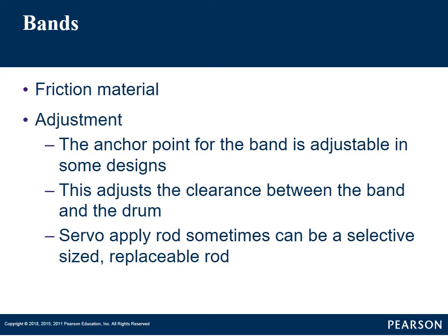Some bands have adjustments to them. There are not very many bands that are adjustable. When we go over servicing the transmission, we'll talk about adjusting bands. But if the band is adjustable, in the sense that you adjust it when you service it, we adjust it because we want to take up the clearance between the band and the drum.